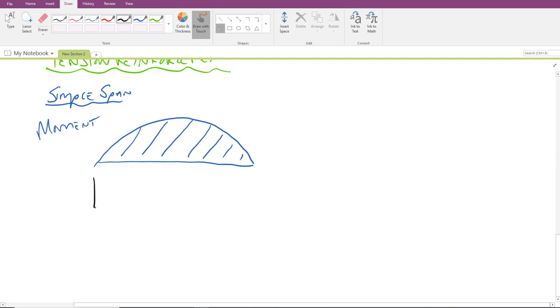And if we put a beam right under this, right here, you'll note that at the outer edges, the bending is 0. So in theory, we don't need any reinforcement out there. The bending is maximum at the center of the beam.